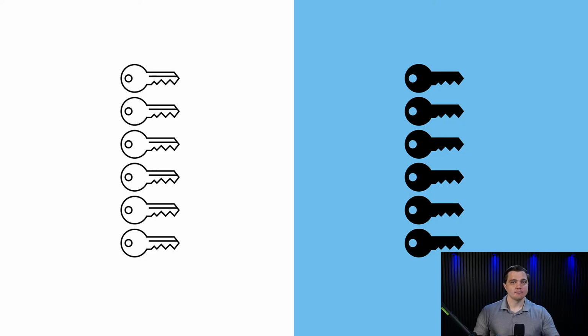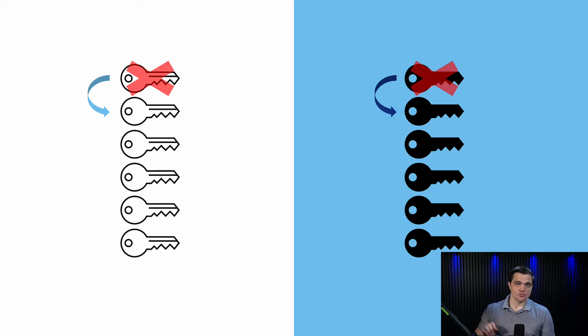Well, you have several private public key pairs that are provisioned to you with every CEC1736 that you have. And again, if your private key gets compromised, we can simply rotate to another key. And you can do this up to 32 times for the CEC1736. Ideally, it's going to be 0, of course. But this is an extra barrier of security that if, again, your private key gets leaked out, if for some reason it gets compromised or cracked in some way, we can simply rotate to another pair and your fleet of devices or platforms, whatever you have in the field, remains secure with a simple firmware update that tells it to rotate to that next set of keys.